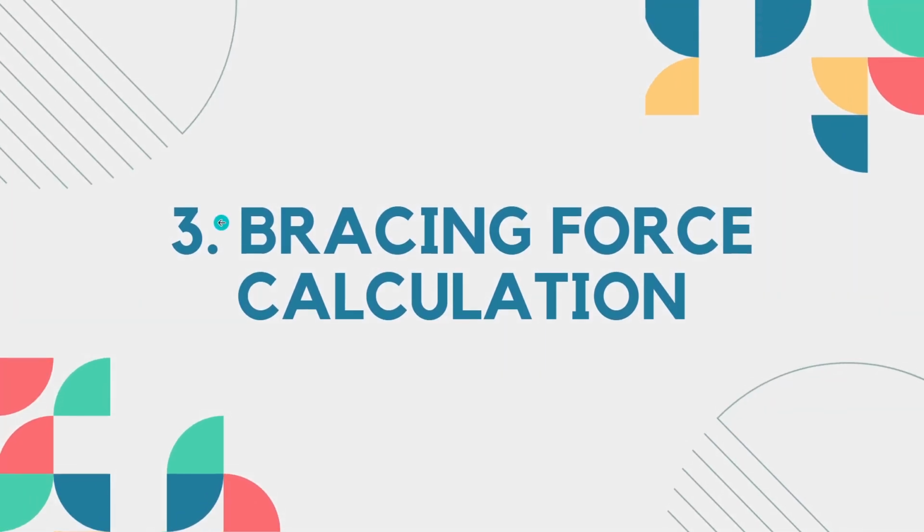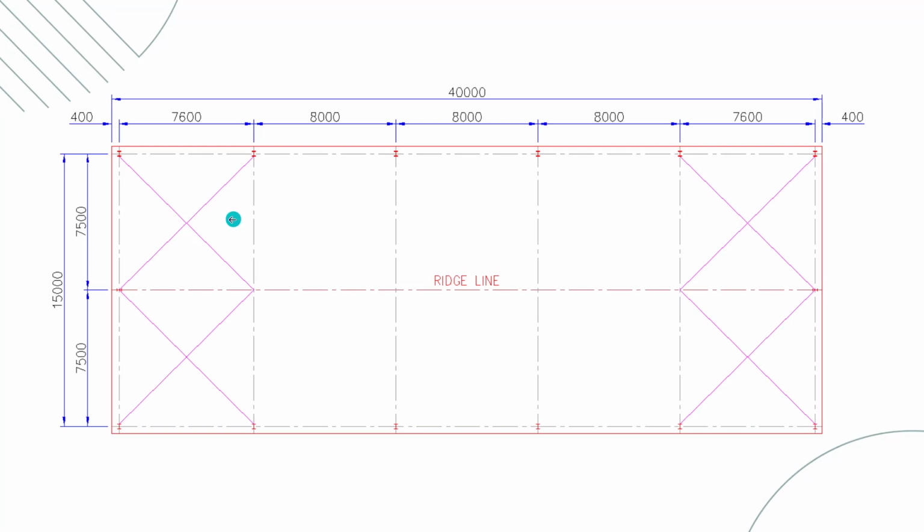Moving on to the next section, that is the bracing force calculation. For the simplicity of the calculation, let's consider this building. As we see, since the length of the building is less than 50 meter, we have 2 brace bays. And in order to efficiently transfer the force, we place them at the end bays.